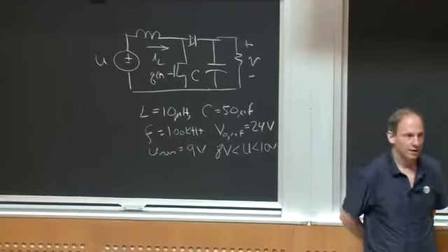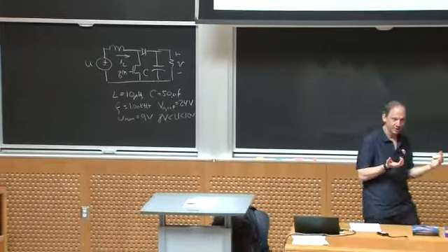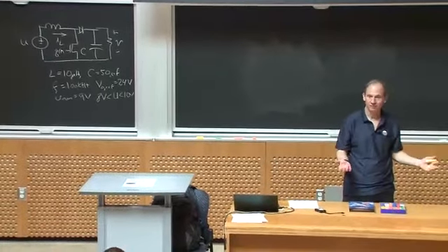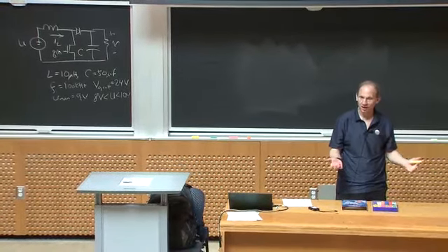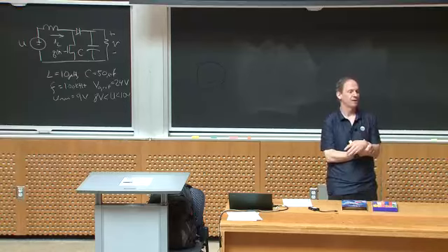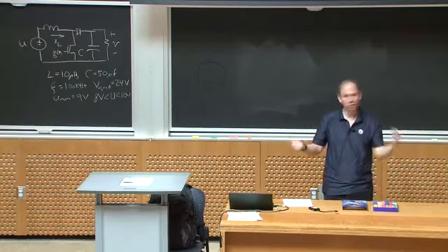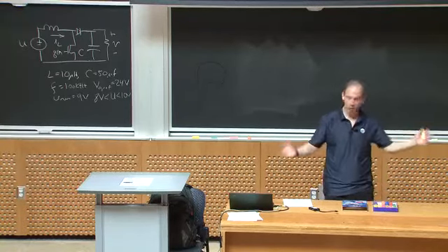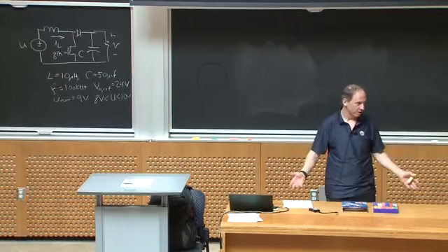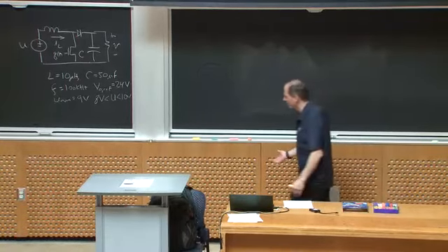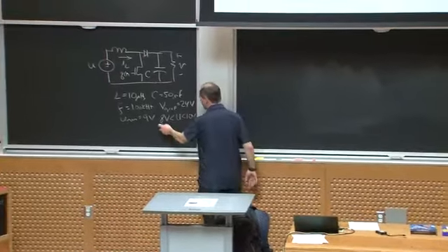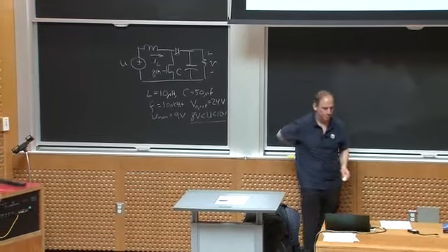Okay? Now, that's a variable range because I want to illustrate to you the impact of a variable input voltage range. But that's a pretty narrow range. I mean, in many converters, 2 to 1 is very typical, 4 to 1 sometimes, depending upon the application, even more than that, right? So I don't want you to get the notion that this is some extreme range. This is actually a really narrow range, okay?